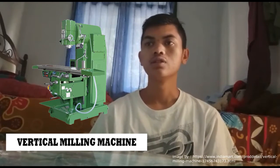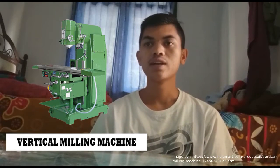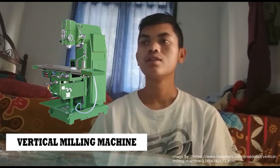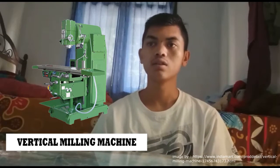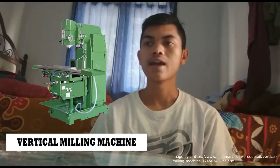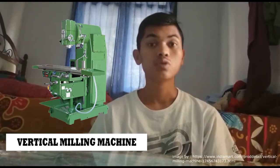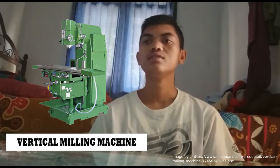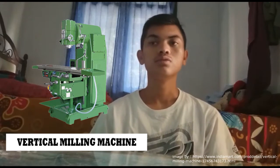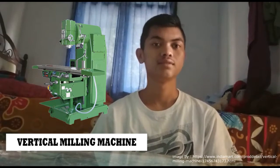The turret mill has got a table that moves perpendicularly and parallel to the spindle axis in order to cut the material. The spindle, however, is stationary; cutting methods can be performed with this by moving the knee and by lowering or raising the wheel. The other is the bed mill, in which the table moves perpendicular to the axis of the spindle and the spindle moves parallel to its axis.